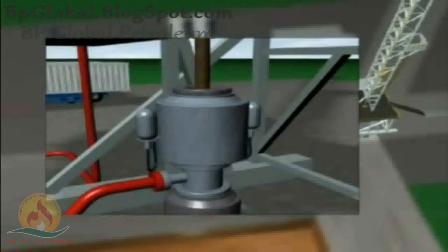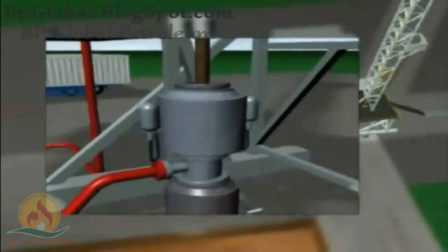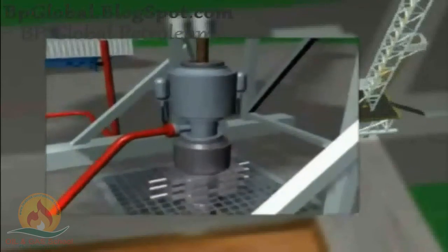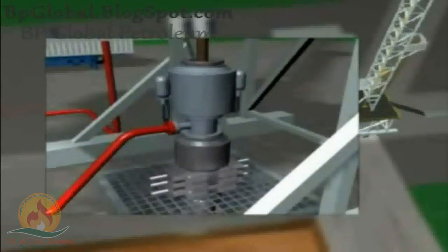and rotate. In some cases, a snubbing unit needs to be installed to allow movement of the drill pipe in and out of the well under pressure. Moving slips on the snubbing unit grip the pipe and push or pull it against the upward force in a controlled manner.